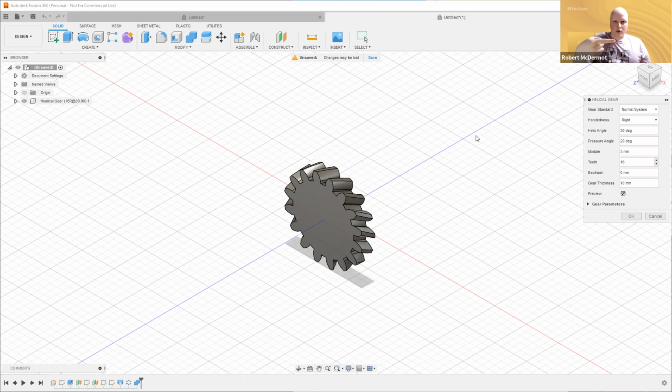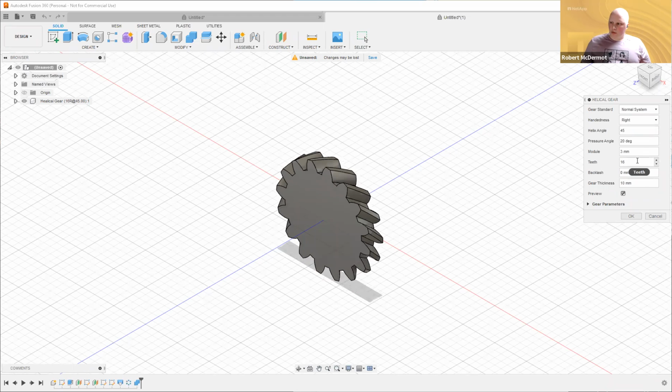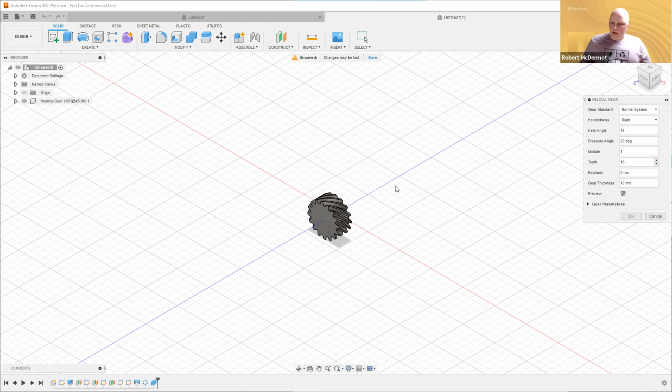You get the transfer motion 90 degrees. And so that's why we're using it here. And so half of 90 is 45. So we're going to make the teeth of each gear at 45 degrees. And we're going to change the module dimension so it's a little more squat and a little bit thicker, right?